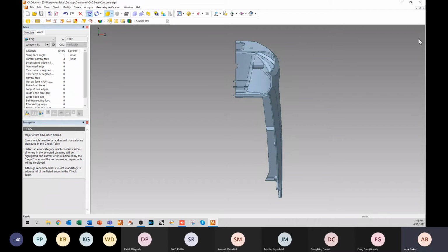All right, but once we're done with CADdoctor, we can go ahead and close out of the application. And it's going to ask us to save the model. This message actually looks like we're going to save the step file at first glance. It's actually going to save the application file for CADdoctor in an extension DRFX MDX, and that's essentially just going to be a save point for CADdoctor itself.